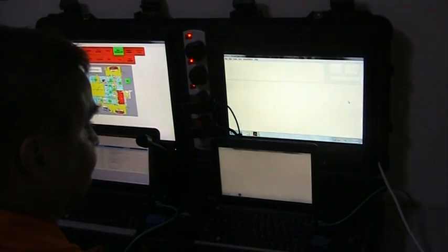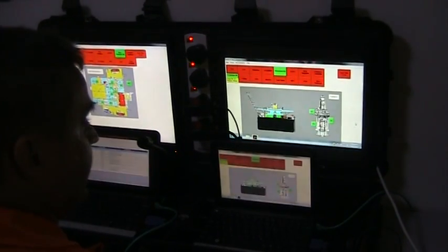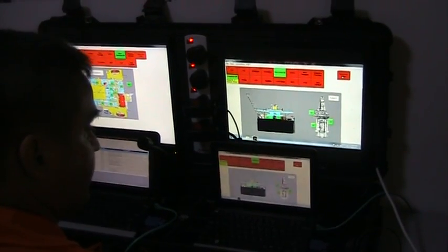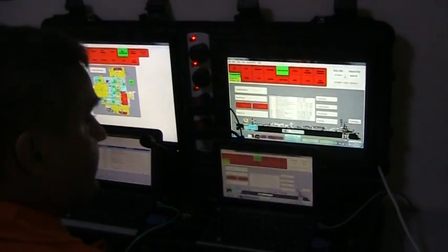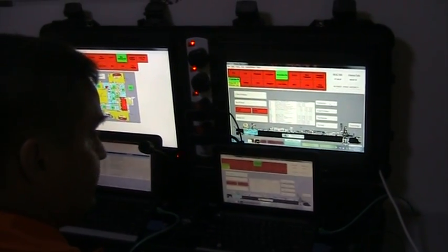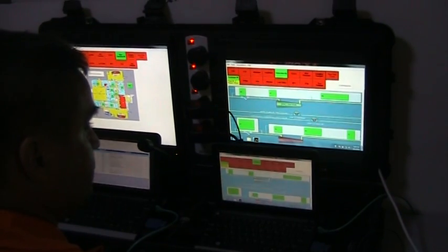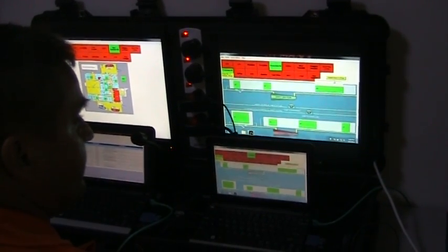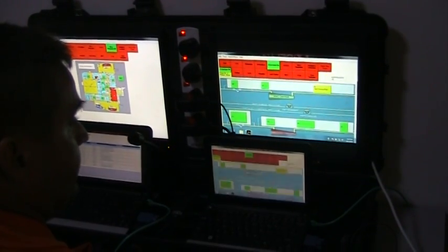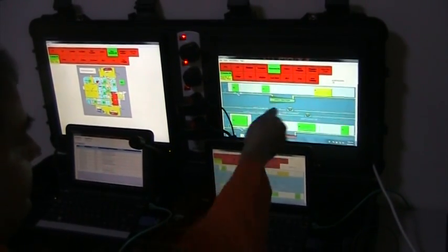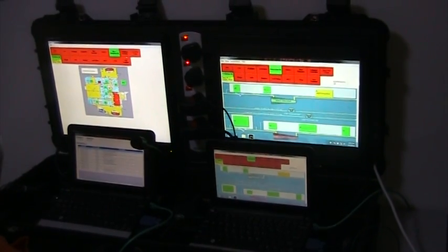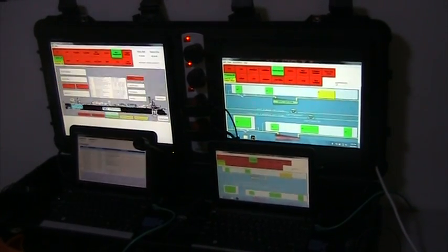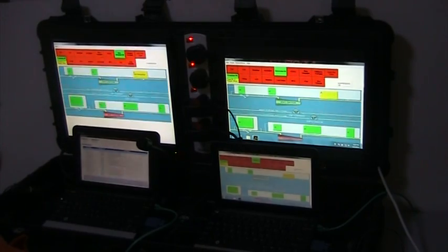Test separator, the turret and bow area, gas detectors, fire detectors, smoke detectors, manual activation call points. Here's the compressor module, a pressure detector. We have set in nominal figures. We may activate. We now have a high warning 80 psi pressure detector in the gas compression module on board this particular FPSO.